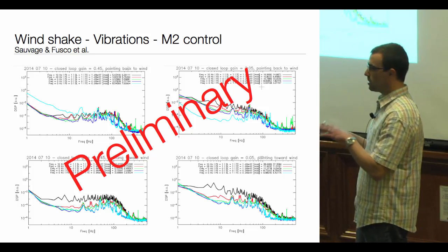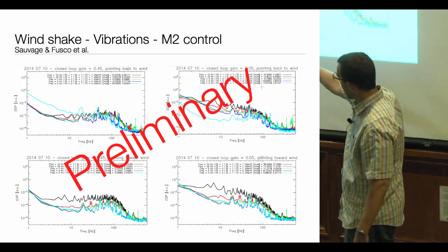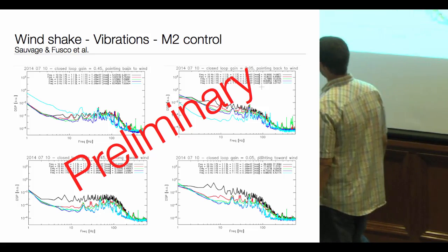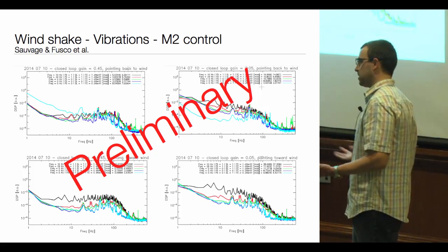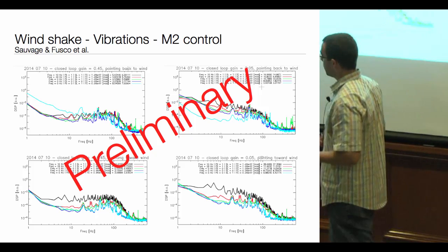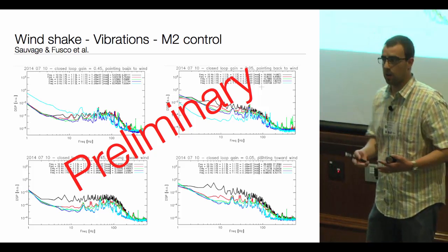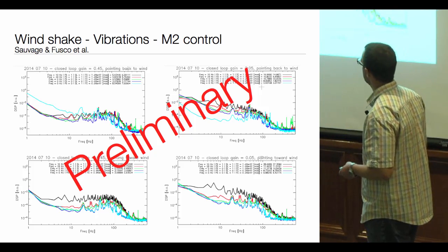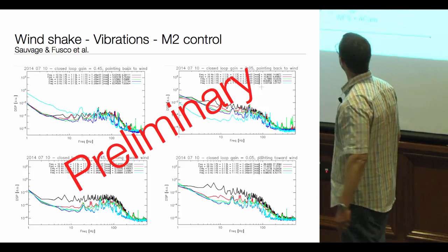So we don't do any field stabilization, M2 is off. And this forest of peaks, high frequencies here, were actually created by electronic noise in the servo loop control of the secondary mirror of the VLT, which has been working like that for the past 15 years. And everybody was happy about it. It's simply the fact that we are exploring new regimes now, and we are seeing things that were invisible before to people. So we are learning along the way about the whole facility.